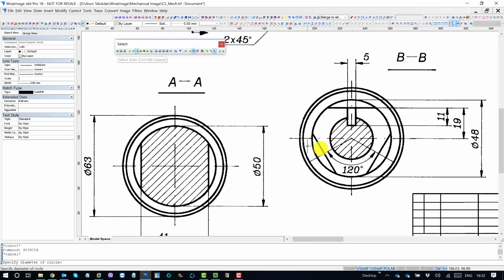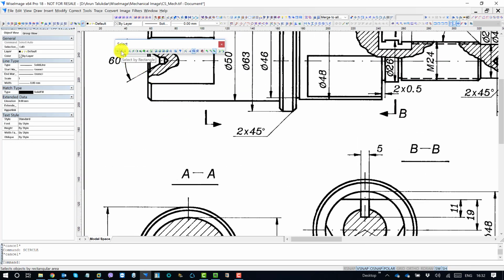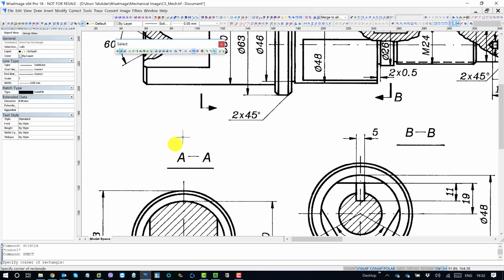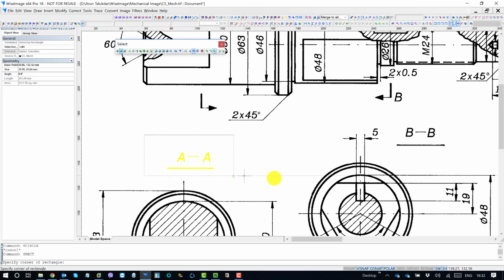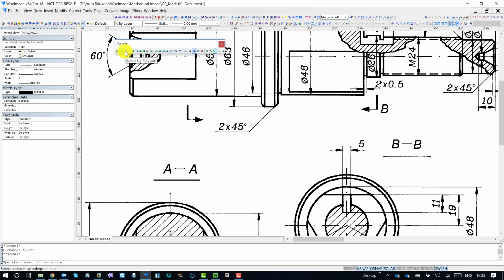So when I select the objects, I should move from that particular function and move to auto again, because this should be the default. What the select rectangle means: I'm still on raster selection, so if I click rectangles, this is quite simple. I can select anything, making a normal rectangle. Whatever objects are in the rectangle, those objects will be selected. And this is quite useful as well.